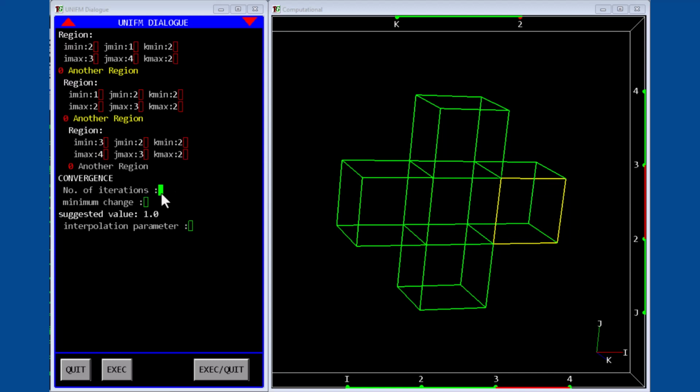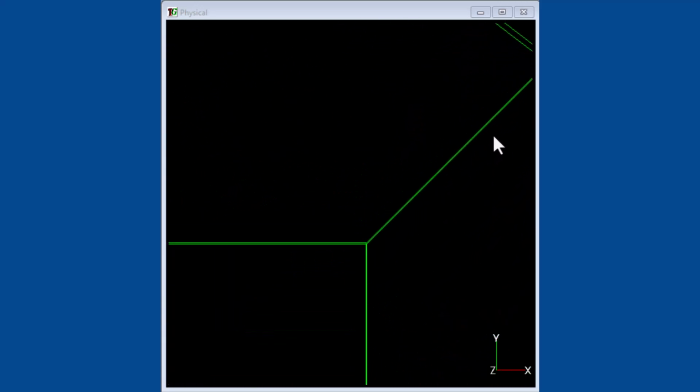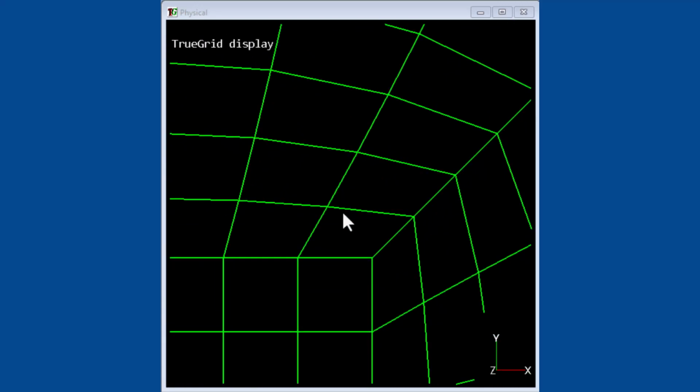The smoothing algorithm is made up of a set of differential equations that systematically adjust the nodes to smooth the mesh. As the iterations of the smoothing algorithm run, the nodes are repositioned to be as close to orthogonal as possible with the adjacent elements, one after the other, until the node movement becomes 0 or close to 0.